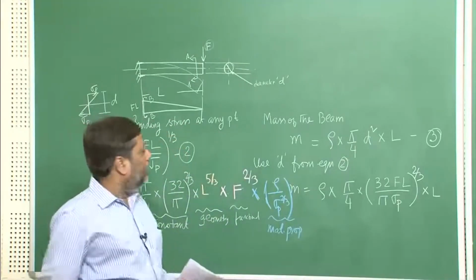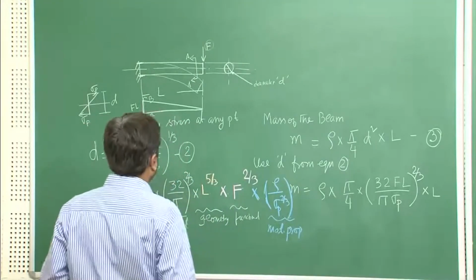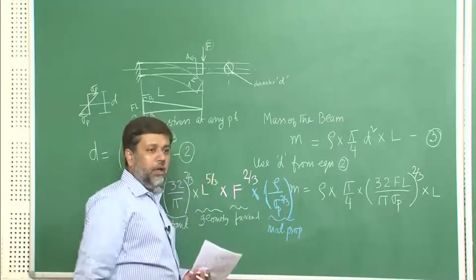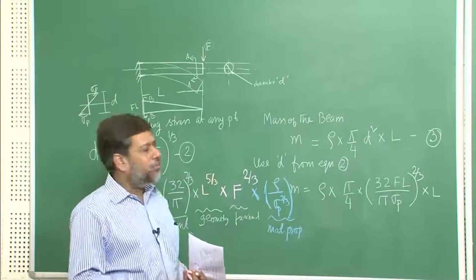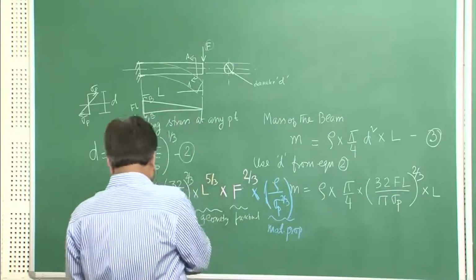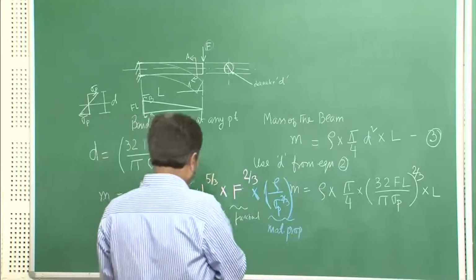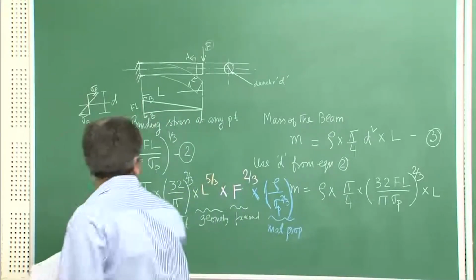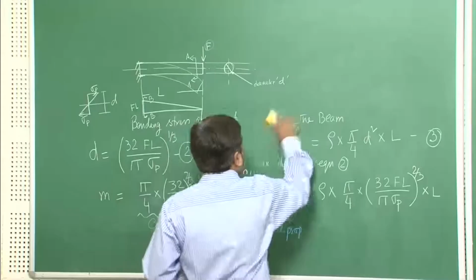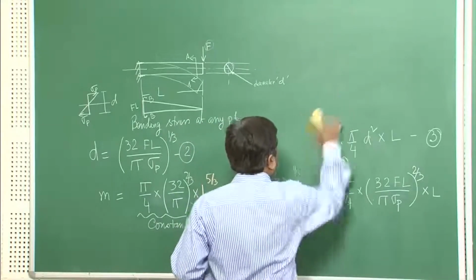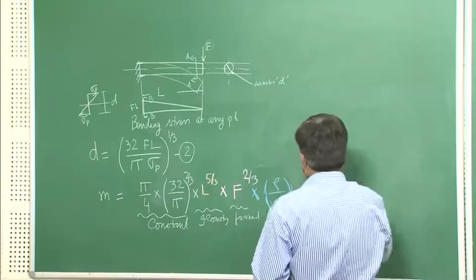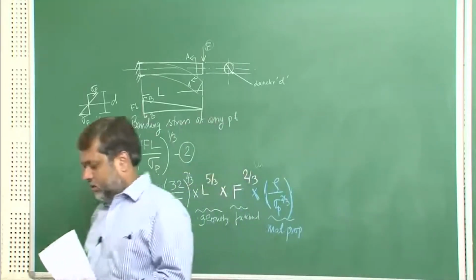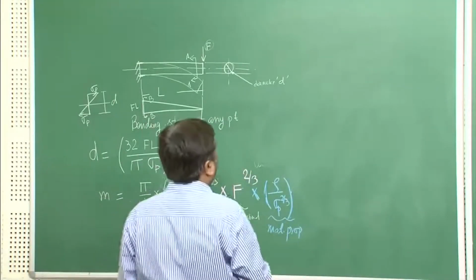Now, you may ask what is this sigma p, how can that be a material property. Well, sigma p is the maximum stress coming to the system, and for many safe engineering designs we can at most take sigma p equal to sigma y, particularly for linear elastic systems.